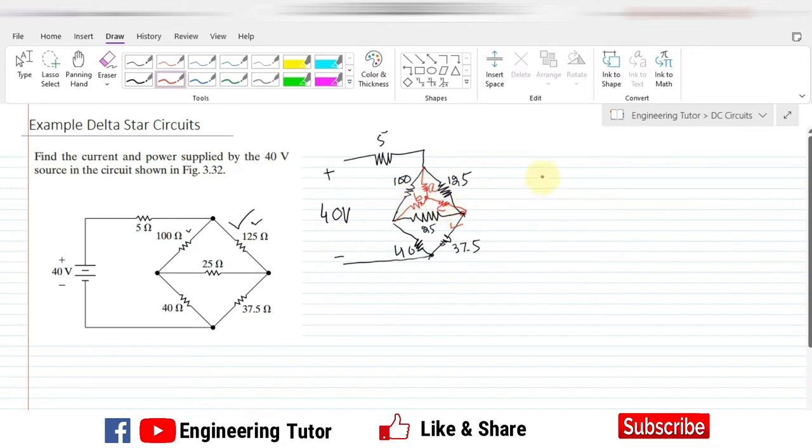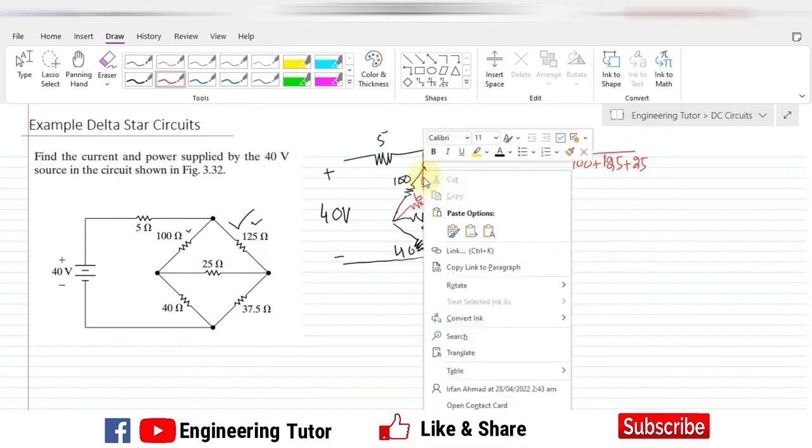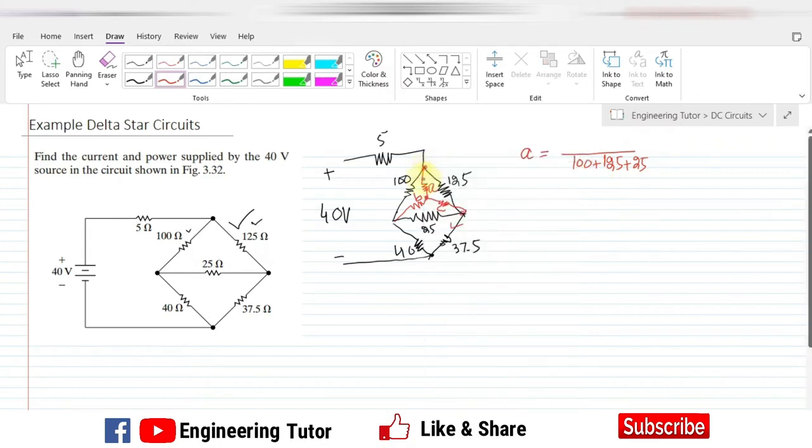So in order to find the values of A, B and C, we have a formula. The value of A can be found by adding all the resistors which are connected in a delta configuration, and these resistors are 100 plus 125 plus 25. These are all the resistors which will be in the denominator, and in order to find the numerator, we have to look for all the resistors which are connected with this point.